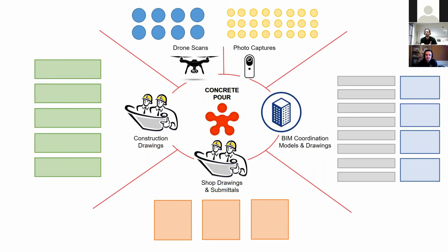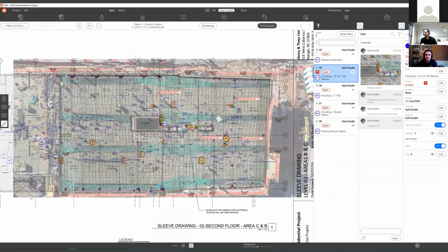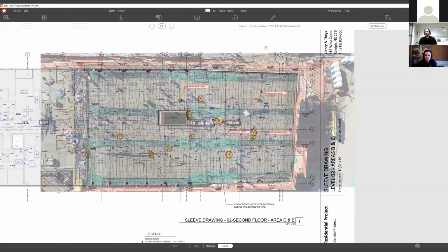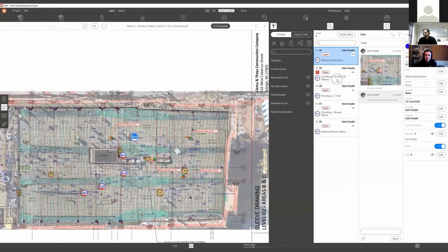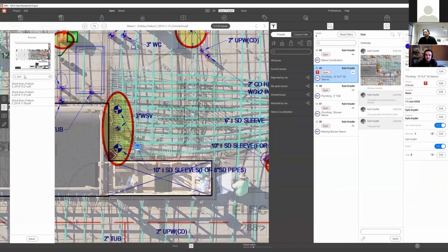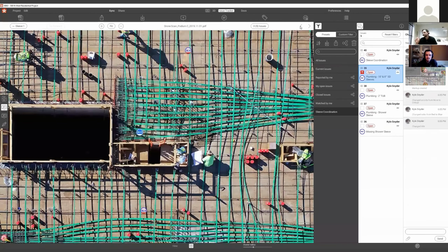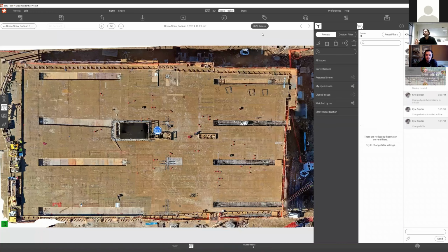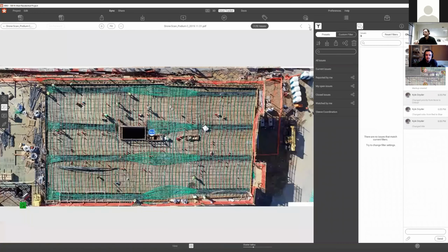So this is where I'm really using Revizto for, and we're definitely looking forward to some other workflows we could do with it. But the cool thing about this is now when I bring in this overlay document that I just referenced before, and I overlay it in the software, much like I showed with that 2D drone that we were able to overlay, now if I have these multiple drone flights in the software, I can, by dropping a stamp or locating it in 3D, quickly flip between all my drone flights.